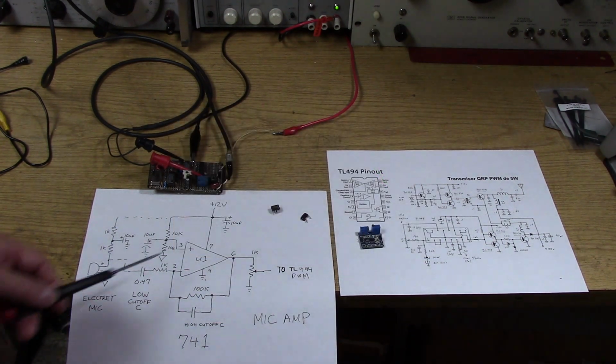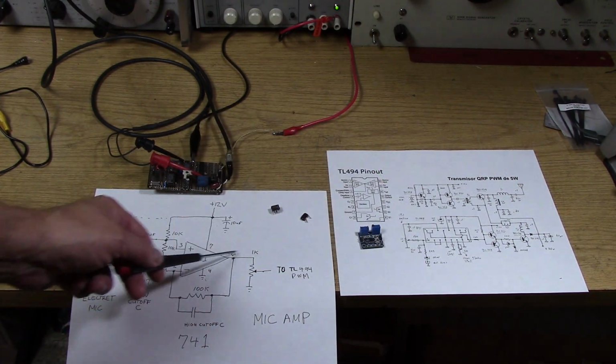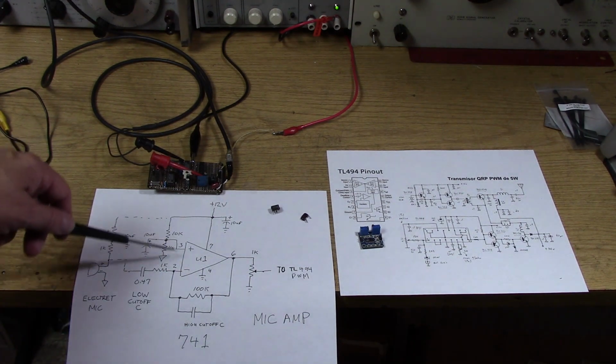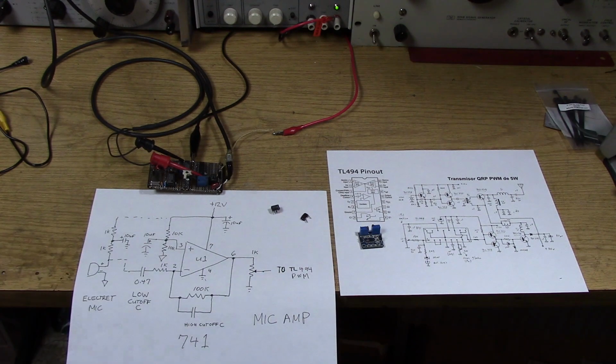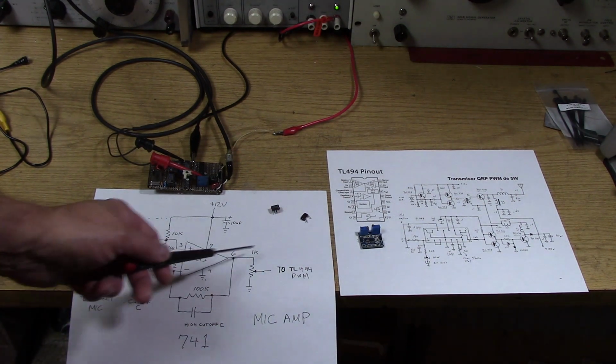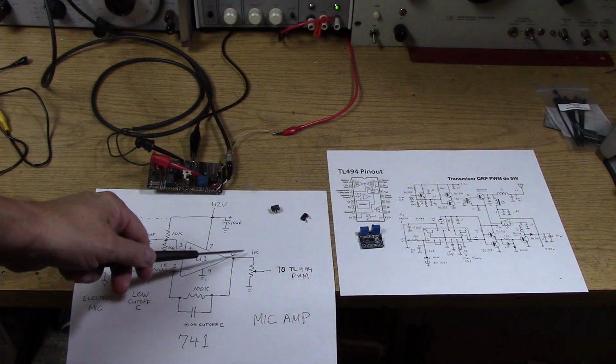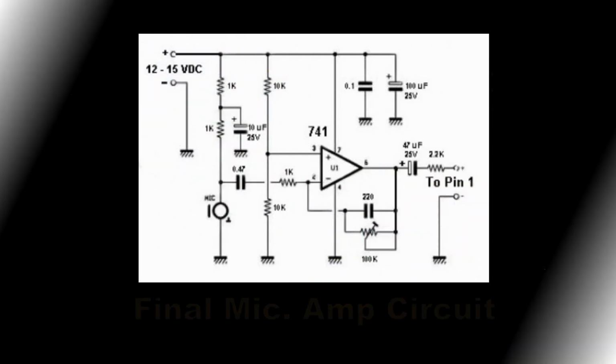And you'll notice I've got a 1K resistor nailed onto the output of the amplifier. Remember, we're making 6 volts here, so there will be 6 volts there. And you're saying I'm shorting that 6 volts with a 1K potentiometer. No real problem there. It's just a few milliamps of wasted power into the resistor. You can always insert a capacitor here if you want to.